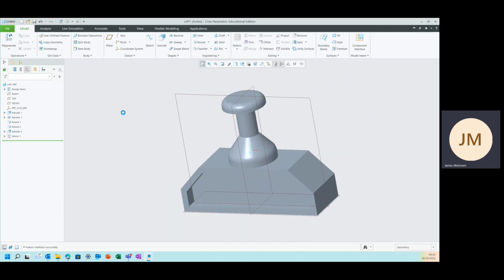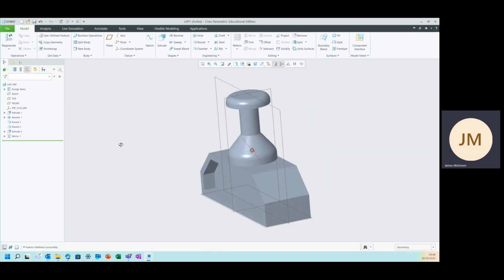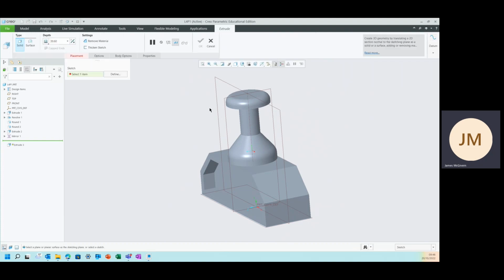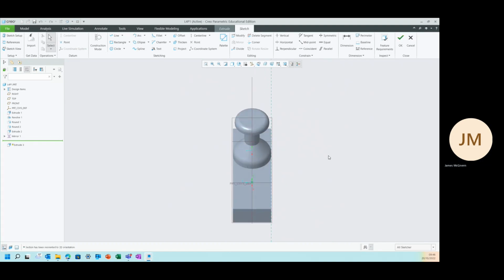Edit an extrusion. Now the final thing I want to do is put a hole here and a hole here, and same on the other side. So an extrusion because we haven't used the hole tool yet. So extrude, and I'll extrude on this surface here. Again, 2D, and this is the surface here. So now I have to pick up the references.